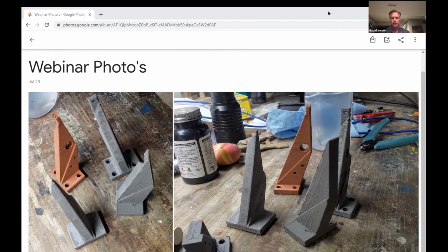I don't know if you've seen the same, Brad, but what I've tried to do is thicken up that infill, and I've had some success using less than 100% infill. But if I can thin out the part so that the wall thicknesses aren't so thick, I'll just go with 100% infill.